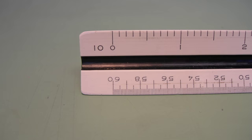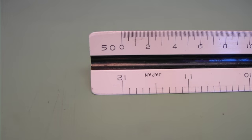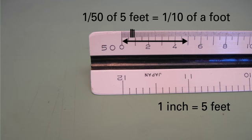You can also take the 10 scale to mean 1 inch equals 1 foot, and then each mark becomes 1/10 of a foot. You can use the other scale graduations in a similar way. For example, you can use the 50 scale to mean 1 inch equals 5 feet, and then each mark is 1/50 of 5 feet, or again 1/10 of a foot.